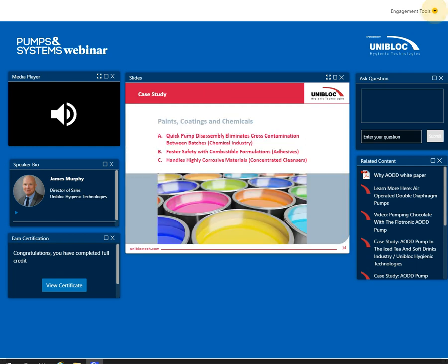All right, let's talk a little bit about paints, coatings, and chemicals. One of the biggest challenges anytime you're pumping a number of different paints or colorants is that we don't want to have any type of cross-contamination of product. So the fact that you can either A, dedicate the pumps per a particular color, or B, disassemble them for cleaning, makes the diaphragm pump very, very attractive.